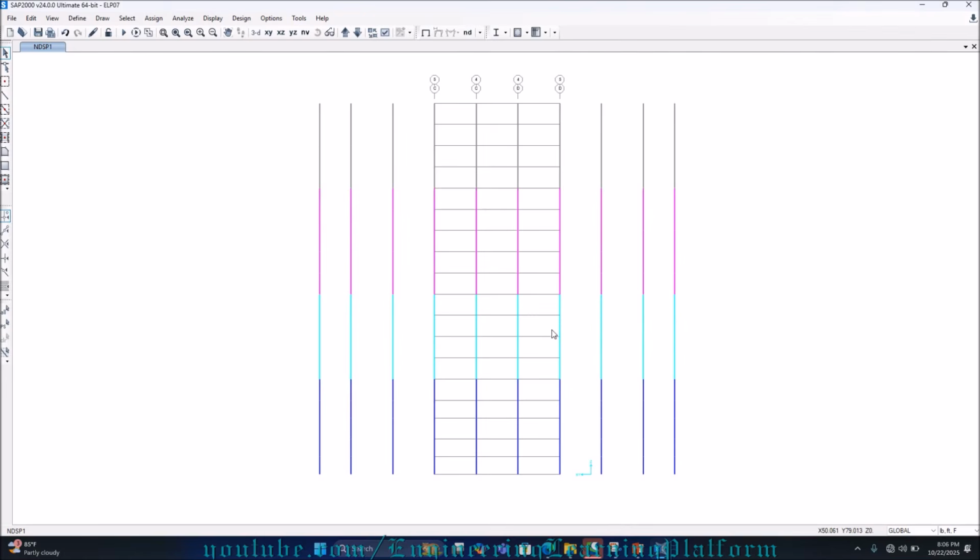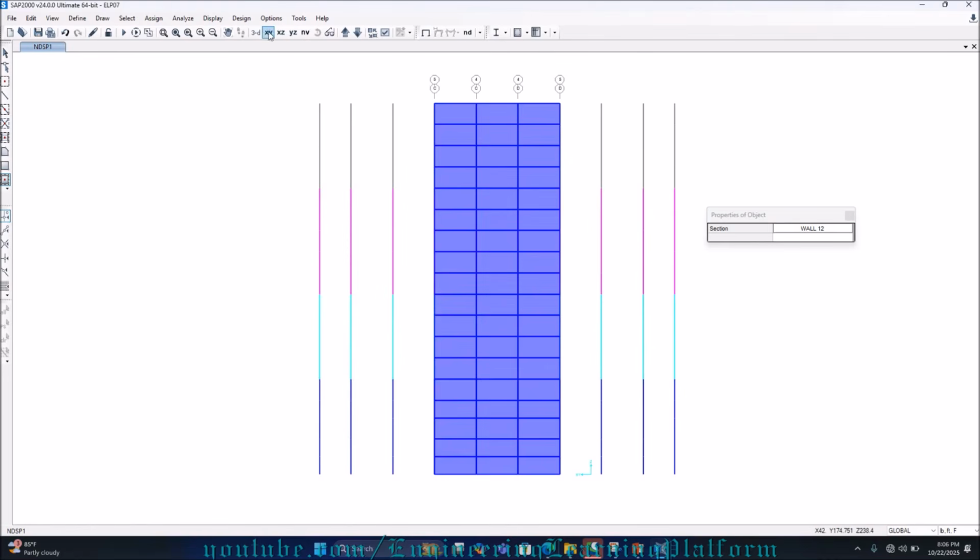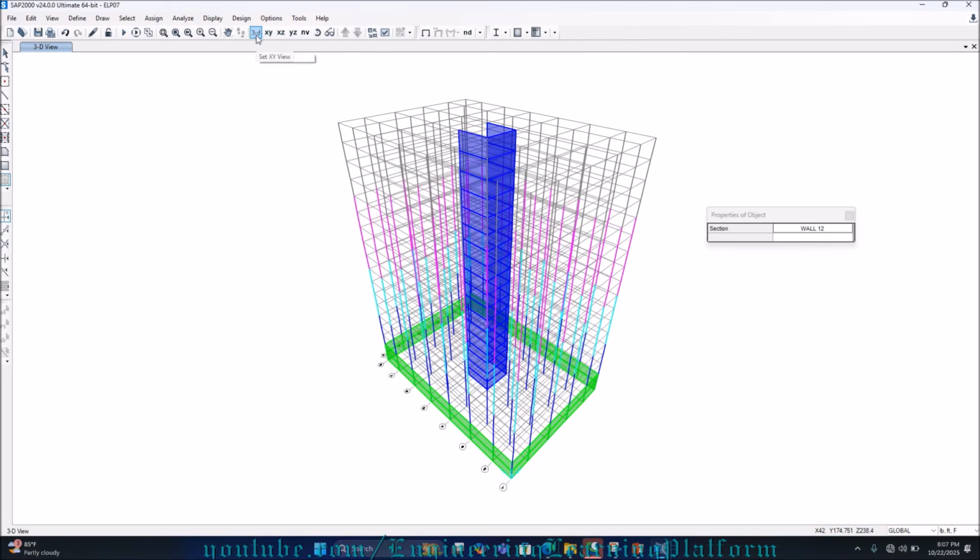Now once you click OK, what you can do over here, you will select the wall. Now your wall will be of 12 inches as I've defined, as I've told you earlier. Our shear wall will be of how much? It will be of 12 inches. You can just click that and you have got your shear wall. Just the one direction is remaining.